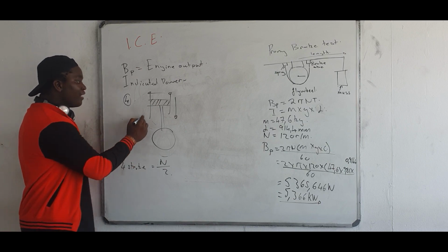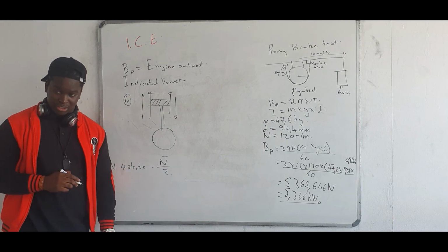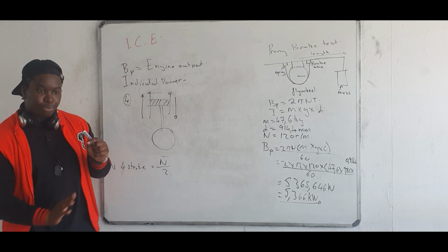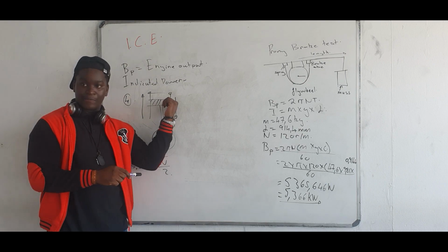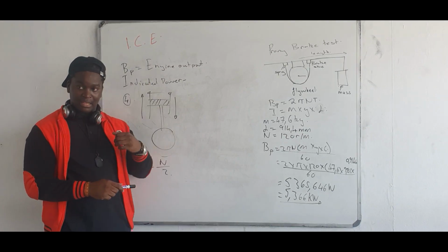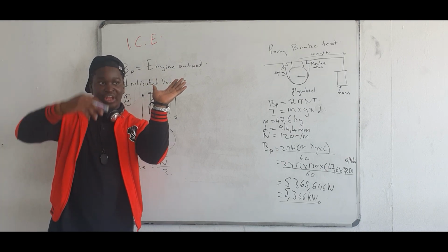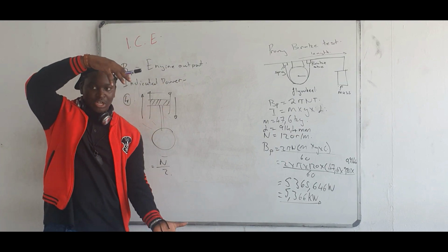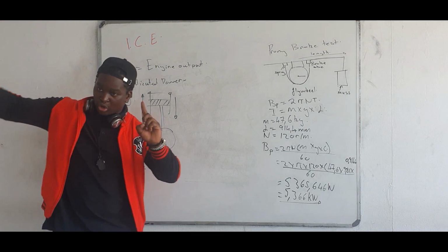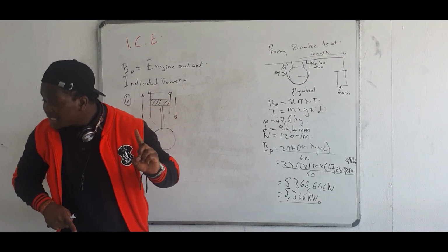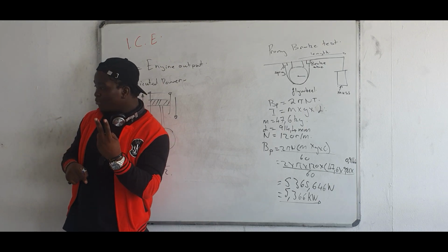Exactly. And every time the piston moves upwards, it's compression and exhaust. Are we together? That means we push it up while we're letting the exhaust gases come out. So the exhaust is here, and the inlet is there. When it moves upwards, it pushes the exhaust gases out, and then it pushes downwards. So that means we only need 1 revolution, or up and down, to produce power, which is 1 revolution, 2 piston movements.